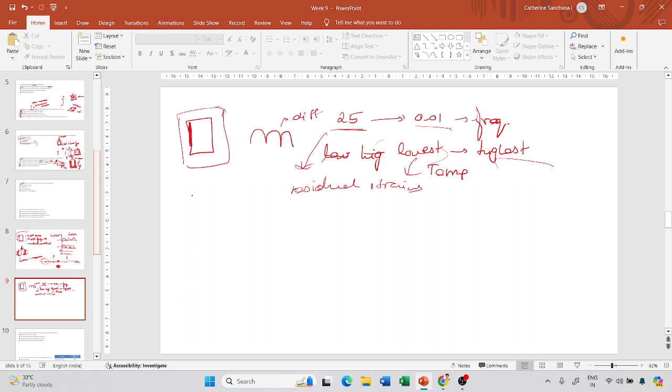Now how much load should I apply? You saw I should apply it at different frequencies and different temperatures. The loading should always be applied such that the material response is linear viscoelastic, and it gives you a particular strain value. For confined there is a particular strain value, and for unconfined there is a particular strain value.